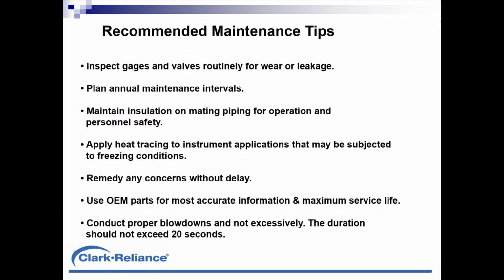Apply heat tracing to any instrument indicating application that may be subject to freezing conditions. There are a lot of applications installed outdoors where this would be a huge benefit. Remedy any concerns before they get worse. Leaks only get worse. Steam damage, steam cuts can happen in valves. The longer it takes to remedy a problem, the more costly the repair can be.